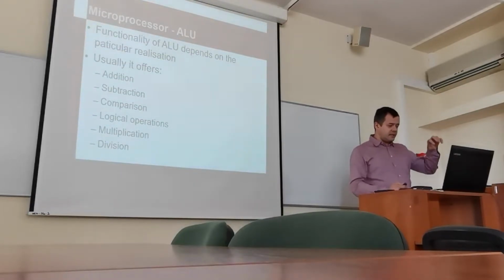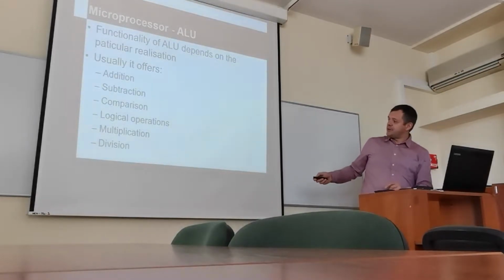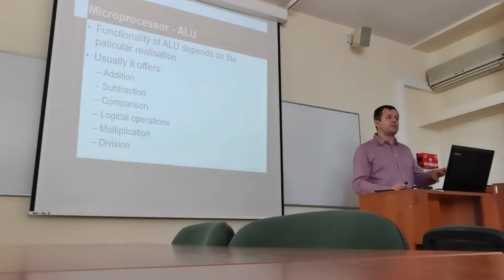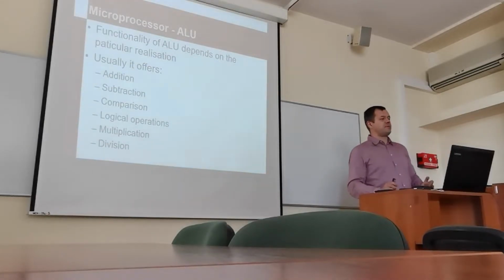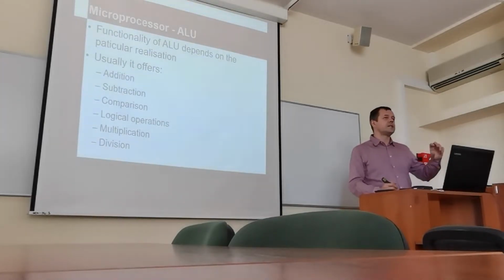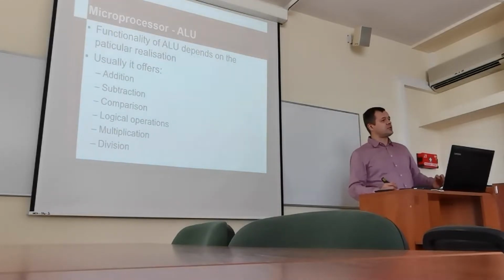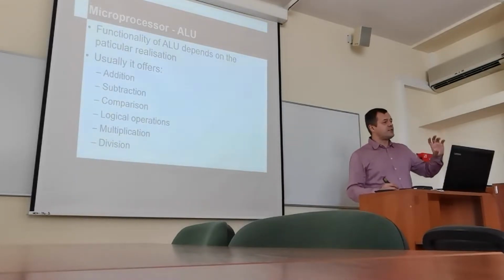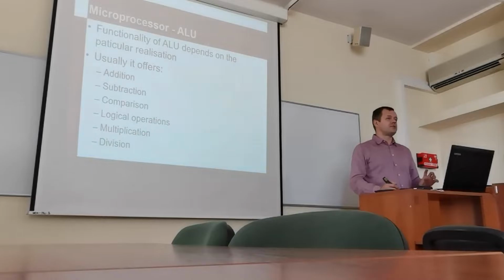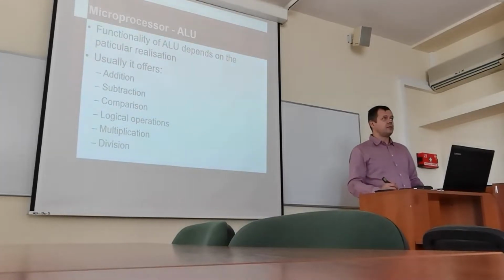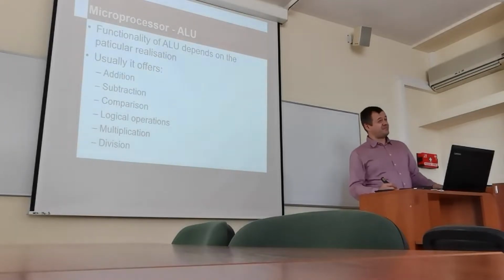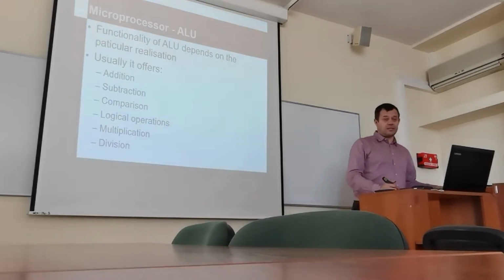It's usually delivering basic arithmetic operations, honestly, without multiplication and division. So I put the multiplication and division here, but as you should remember from introduction to microcontrollers, multiplication and especially division are very resource-hungry operations. And to make them single-cycle operations, in case of division, I don't think it's even possible.